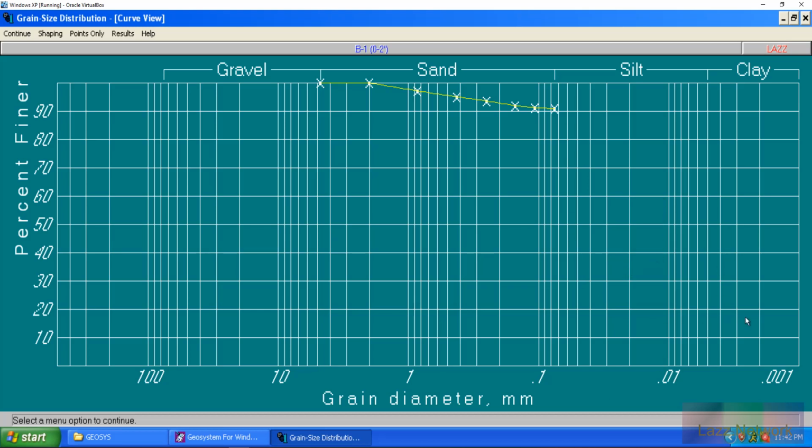So I don't know if I'll show that, or if I even have one, because we don't do hydrometers often, because Florida doesn't have a lot of silts and clays. And even when we do, most of the time they just indicate that it's a non-suitable material, so it just gets removed anyway. So people just don't think about it, unless it's really deep, then they'll work with it and figure out how to engineer with it or around it.